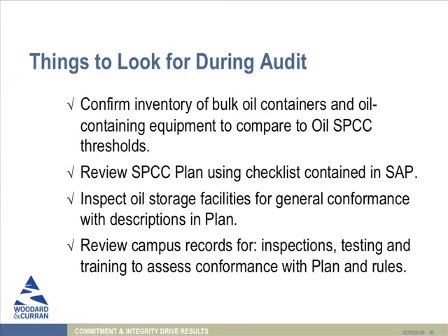Inspect the oil storage facilities for conformance with the plan. Do they have all the secondary containment they need? So when you're doing this, you're not only looking at is the facility in compliance with the oil SPCC regulations and is the plan cover everything it needs to, but is the facility implementing the plan?